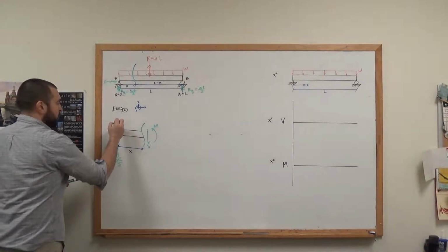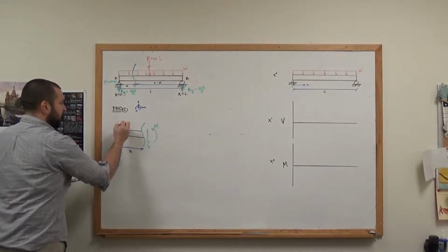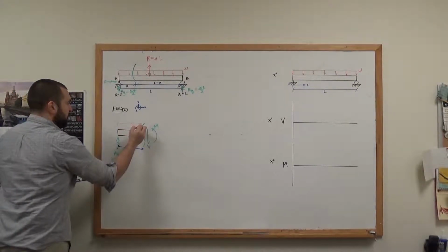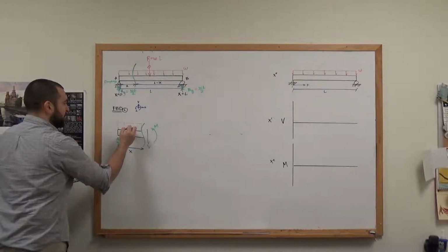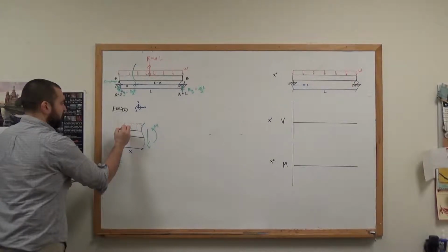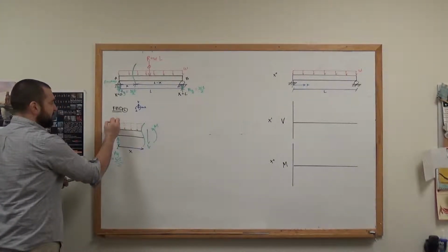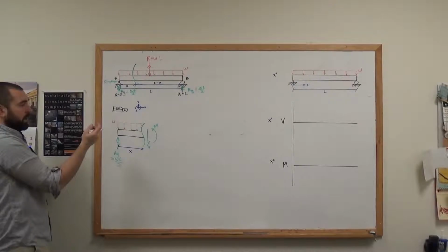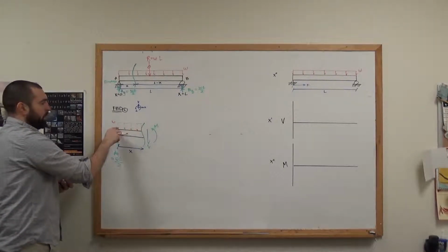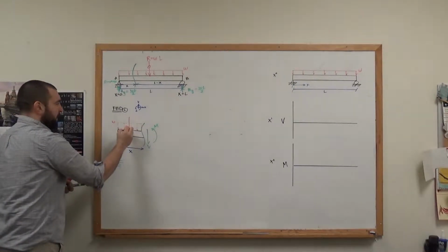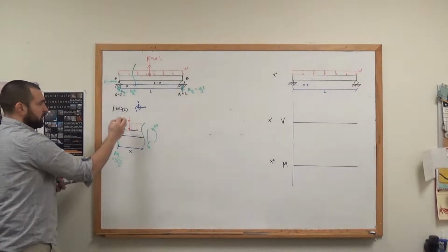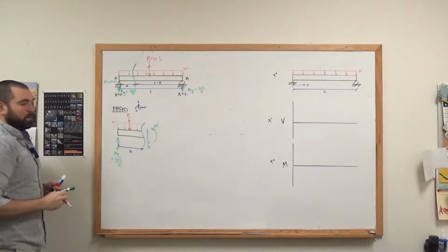some of which is not there. So what I'm going to do is draw a dashed line to show the remainder of that distributed load that remains. It still has an intensity, a height of W, that doesn't change, but this is all that remains. I need to turn this, the remaining amount of load, into a resultant.